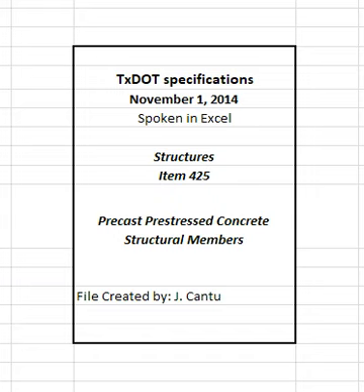Maintain copies of the manufacturer's certified domestic certification form D9-PS1 for 7-wire steel strand and supply to the department upon request. Use 7-wire steel strand produced by a prequalified manufacturer on the list maintained by the Construction Division. The department may take samples in accordance with Tex-710-I to verify compliance with specification requirements.